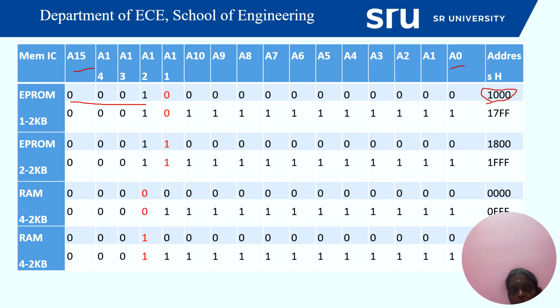And what is the value? 07FF for 2 kilobyte. I have explained in the previous slide. So 1 is 1 only, 7FF, that is the 2 kilobyte capacity. So 1 means 0001, that is the same. And then 7 means 0111, F means 1111, again F means 1111. This is for EEPROM 1.